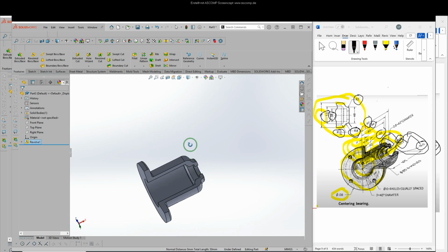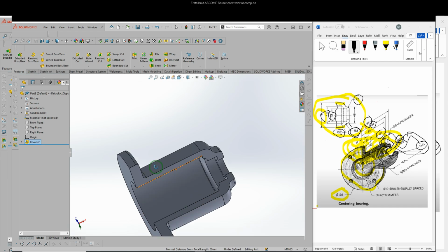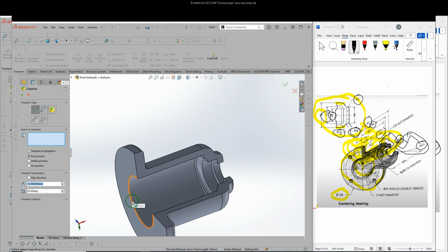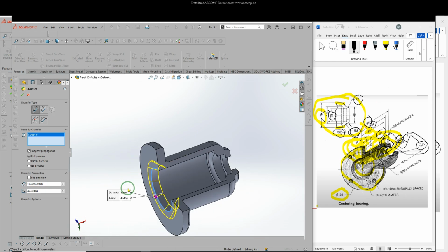The 3D model is now formed and ready for further features like walls and chamfer. Now select the chamfer tool and apply it to this arc. So for that, here we can see fillet. Click on the down arrow here. Click on chamfer, and we have to add a chamfer on this arc.